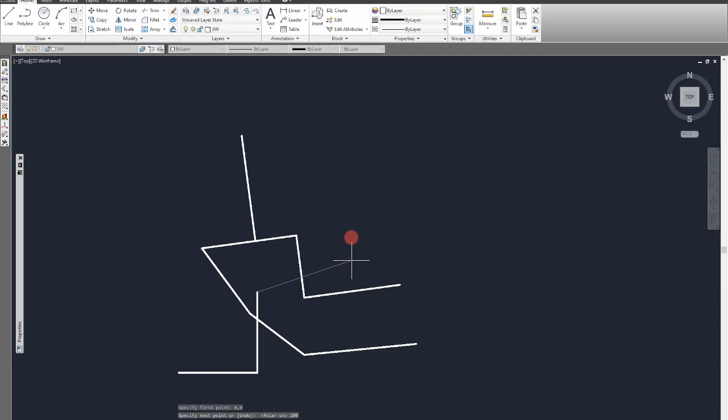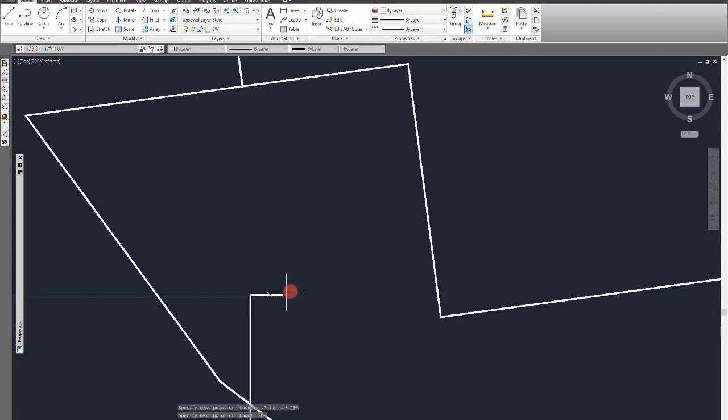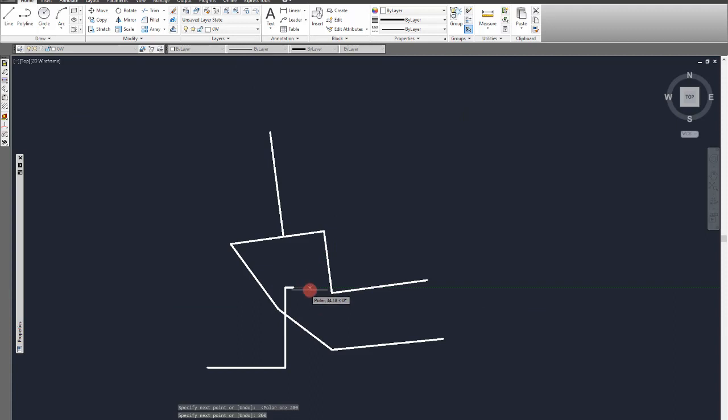And now if I want the next point to be relative, with relative coordinates, to the previous point, not to the coordinate beginning, I will type this sign, which is of course by shift clicking the 2, and I will type 20, 0. This will make it 20 in the horizontal direction and 0 in the vertical. That will make a 20 length segment along the horizontal.